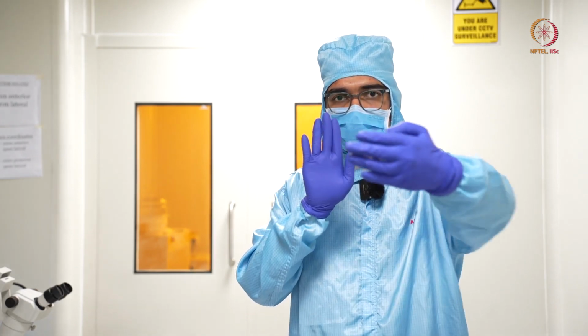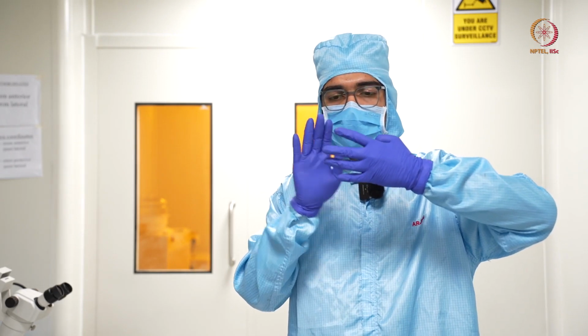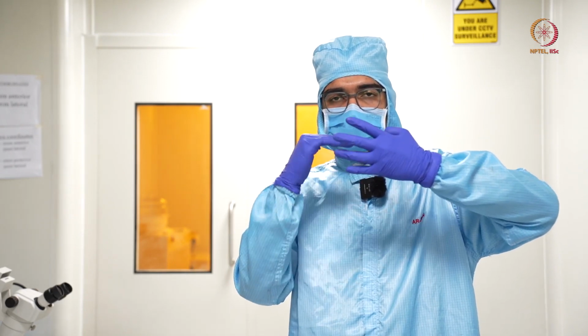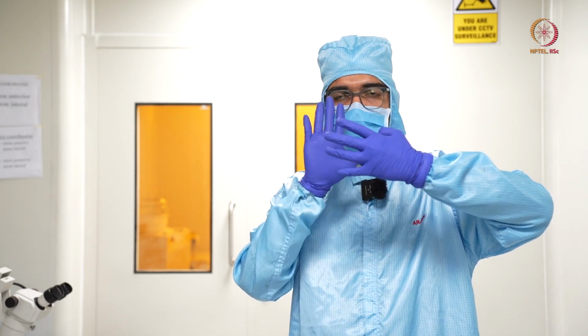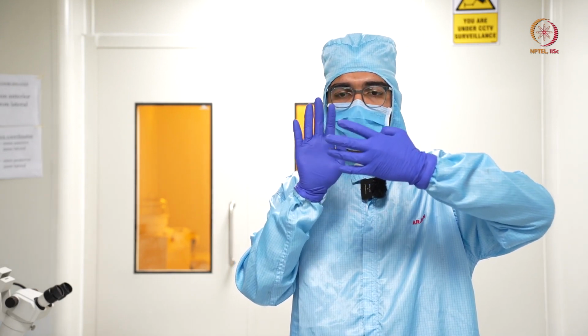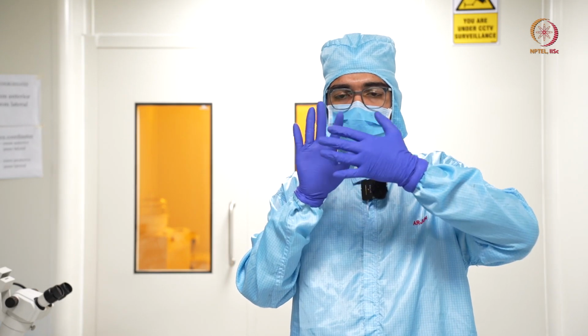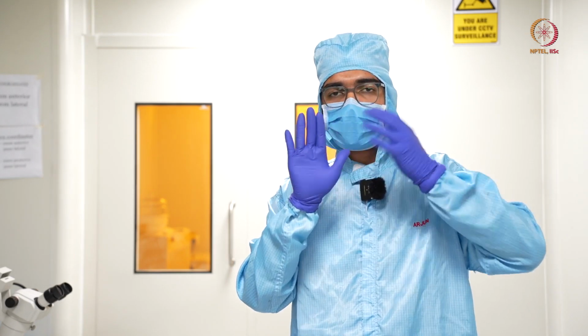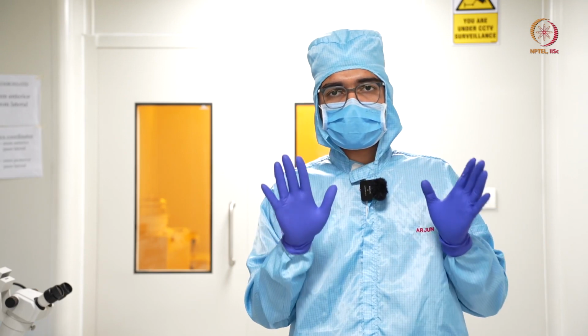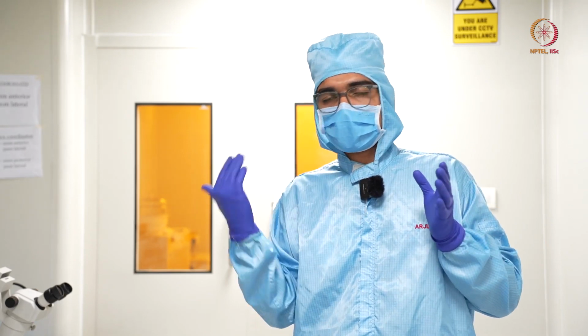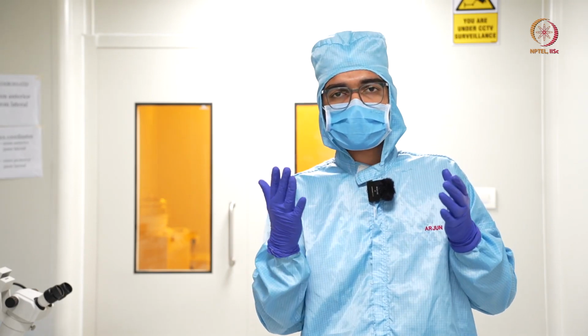So it's like if this is a finger, and I have the substrate with photoresist coated kept here, and the light source comes from here. Then the light passes through these gaps in the fingers and falls on the substrate. Now wherever the light fell might have a different property than wherever light has not fallen. So this is the principle of photolithography, and we will further see how this actually happens.